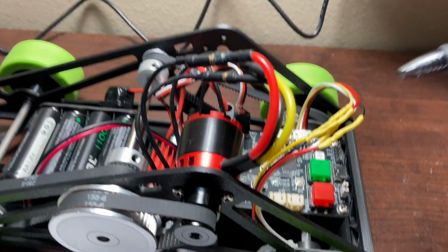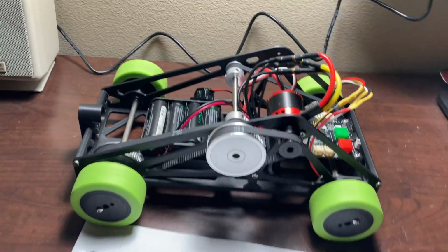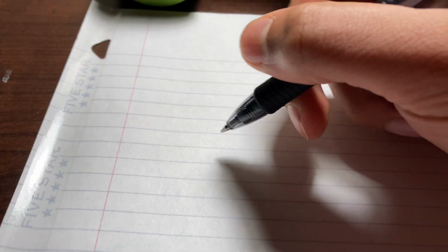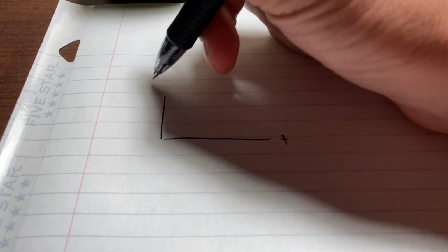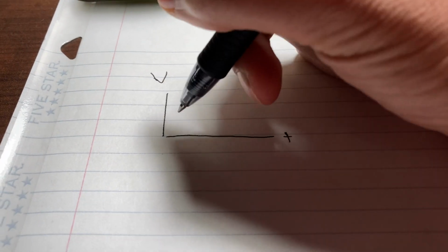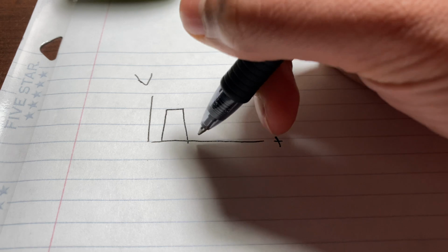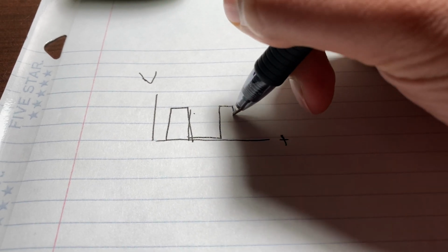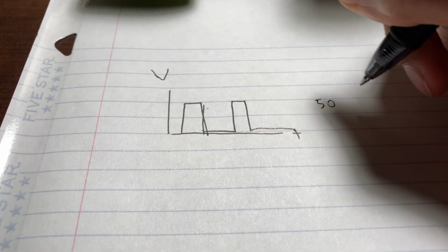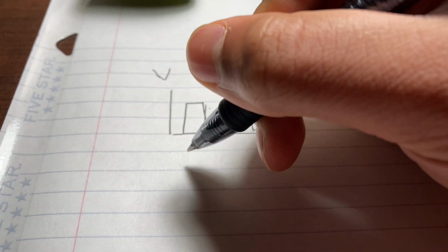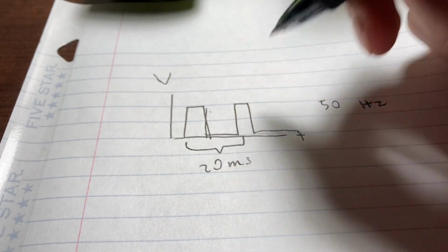So what's happening on the signal wire is the chip on the board is sending a PWM signal to the ESC. So what's a PWM signal? Well, basically, let's say that you have a signal, right? So this is time, and this would be voltage, right? Essentially what happens is that it turns on for a short amount of time before turning off. Then it keeps on going, turns on again, and this is constantly repeating, okay? So this happens at 50 hertz. What that means is that this total amount of time before it repeats is 20 milliseconds.